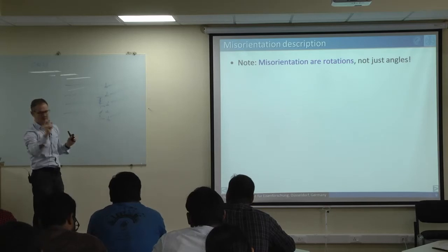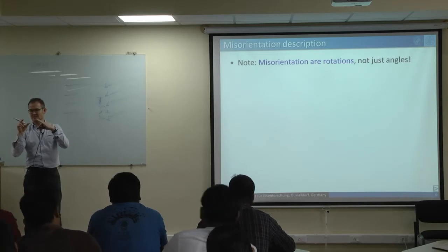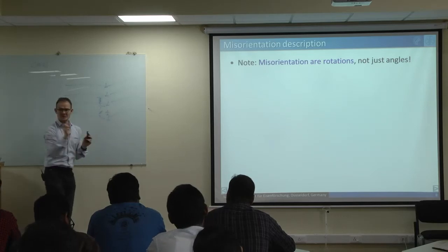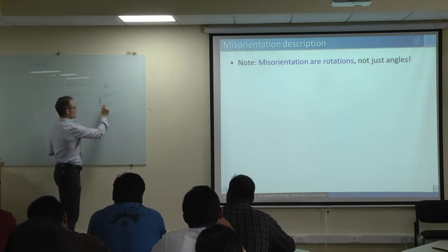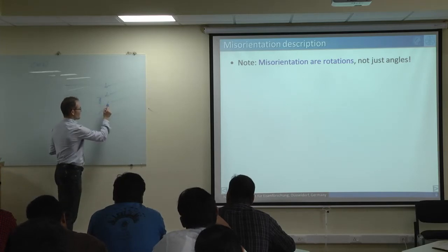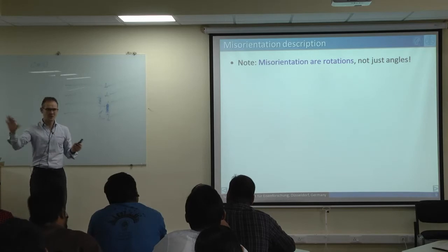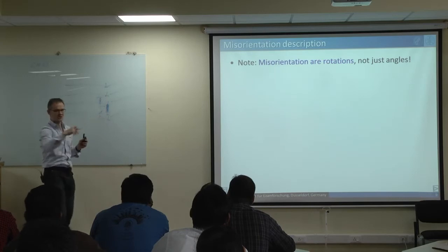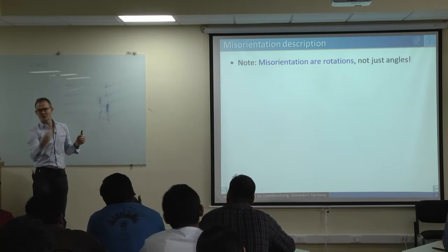When you have 1 degree misorientation, you have a dislocation about every 50 nanometers. And when you have 15 degrees, then you have a dislocation every 2 nanometers or even less. At 15 degrees, the dislocations get so close that the cores of the dislocations overlap, and at this moment the dislocations move together. There is no dislocation any longer, and the grain boundary behaves completely differently than before. It's no longer separated by individual dislocation features, but by a kind of amorphous feature.